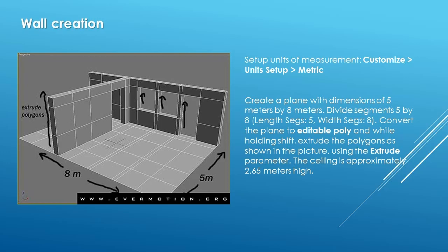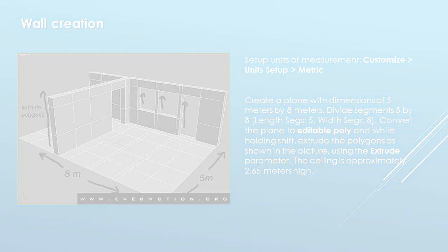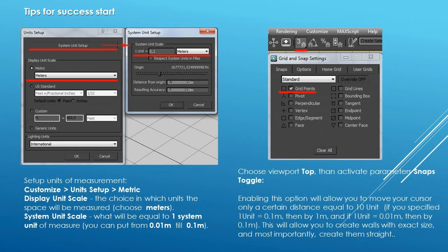You can use the Quick Slice button from the Edit Geometry rollout to create additional edges. If you need to connect vertices together, use the Collapse command button. If you need to connect edges, use the Bridge command. Here are tips to do your work more conveniently.